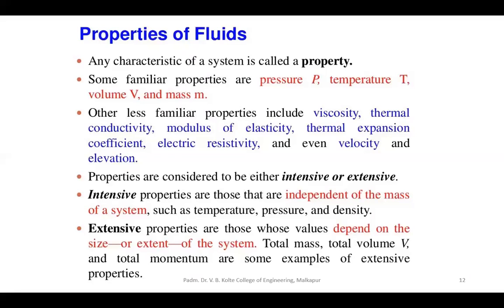What is meant by intensive? What is meant by extensive? Intensive properties are those independent of the mass of the system. See carefully. Intensive properties are those that are independent of the mass of the system, such as temperature, pressure and density. Pressure, temperature and density do not depend on the mass of the system. So this property is called an intensive property.